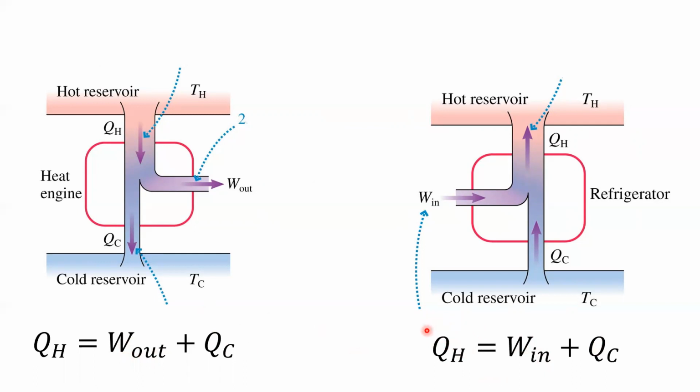So here, the overall heat that gets dumped into your kitchen, the air of your kitchen, would be the heat taken out of the interior of the fridge plus the electrical energy withdrawn from the electrical plug socket. You know what I'm trying to say. The energy that you drew from the power company.